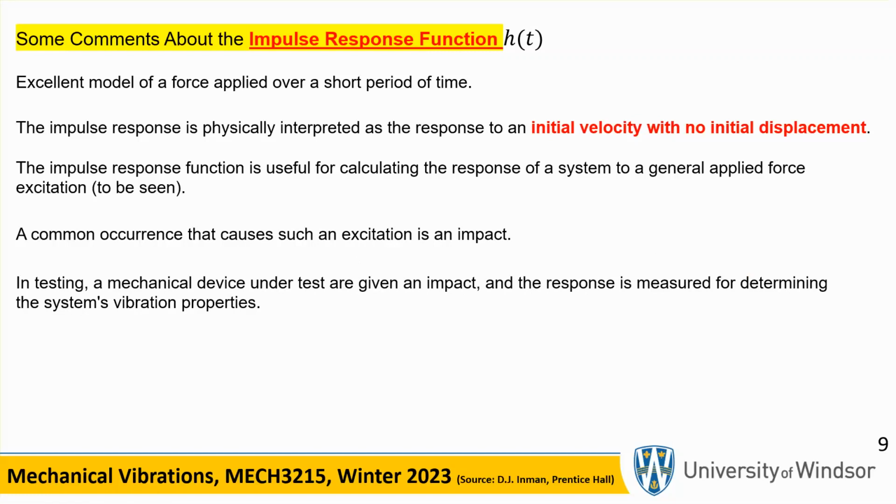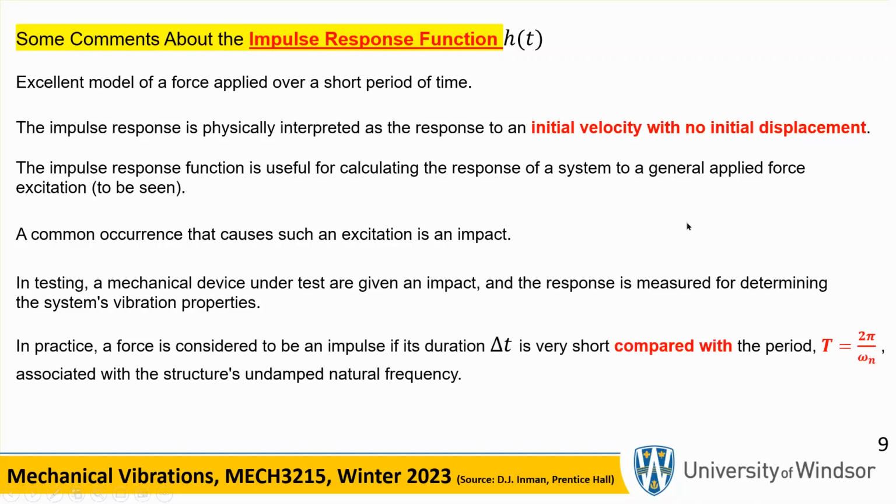Now, in testing a mechanical device under test, usually we hit it with a hammer. That's an instrumented hammer, a hammer test. So that hammer not only imparts an impulse to the block, but it also measures internally, think about it as F hat, or F, the magnitude of that force. That's the role of a hammer.